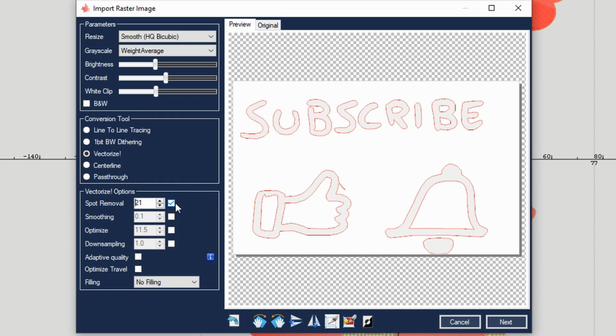Now there are different options, they're doing different things. Some of them are not going to be visually previewed because there are things happening in the background in the Gcode files exactly. So we can apply smoothing. Okay, this will basically render a smoother outline here. Okay, we can also optimize. This is something that happens in the background, so you will not see anything changing here.